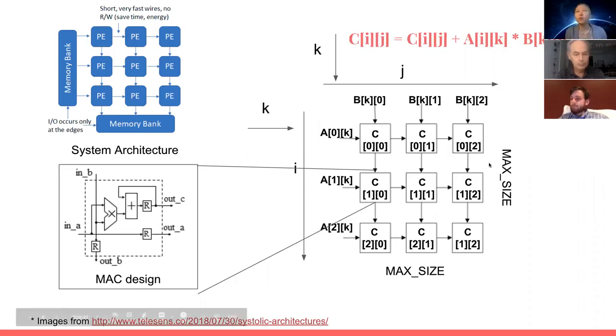So in this example, we can, for example, flow the B with different K into the different C units. Essentially, once we add up each of the partial sums here, we will gather the results of matrix C00, right? Likewise, we can do the same for the other PE units. So by the end of this computation, after we feed in all these inputs from A and B, the register C in each of the PE array will store the outputs for the output matrix.